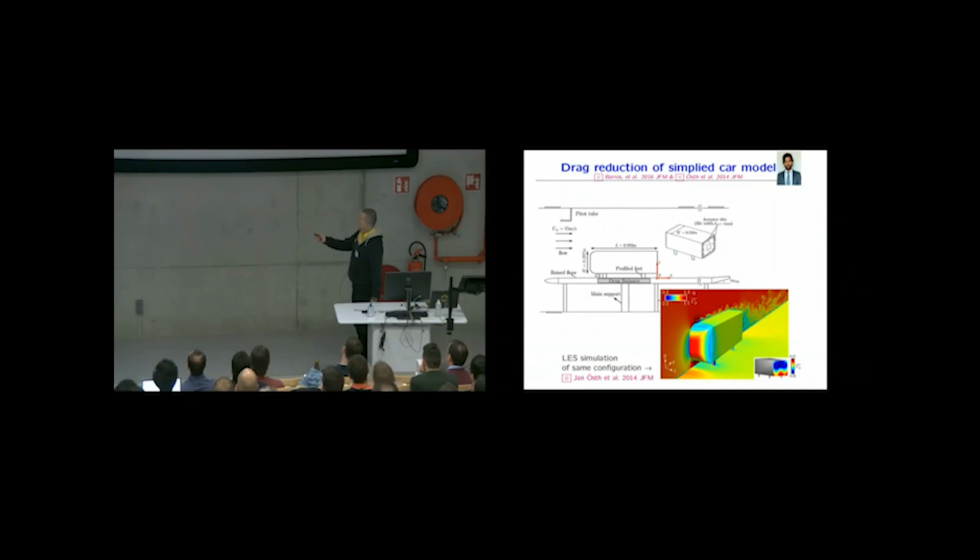The flow comes from left to right. The Ahmed body is mounted on a drag balance, so we can measure the drag directly. We have 4 independent actuators here. We have something like 12 sensors here. So now the name of the game is to use these pressure sensors to determine an actuation which minimizes the drag somewhat.